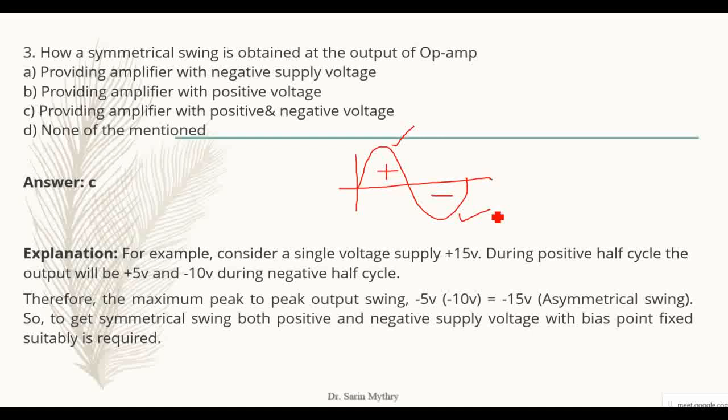But what happens in the practical scenario? The op-amp is going to enter into its saturation stage at one particular voltage. As per the research that has been conducted, the swing of your output voltage can go up to only 90% of the power supply which is given to it.